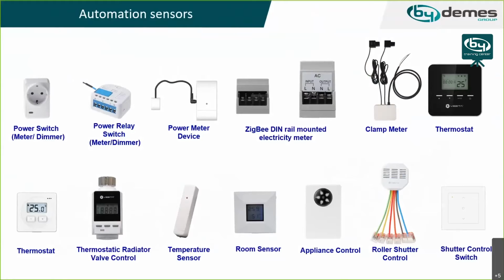And here we have automation sensors. In this case, we have power switches or plugs, power relays, and thermostats. The thermostats are very simple. They have one relay output, and it starts triggering the relay depending on the set point of the temperature you set. If you set, for example, 22 degrees, it will start switching the relay on and off until it arrives at the set temperature.